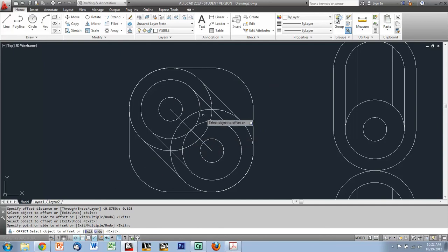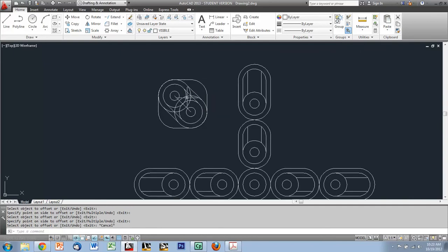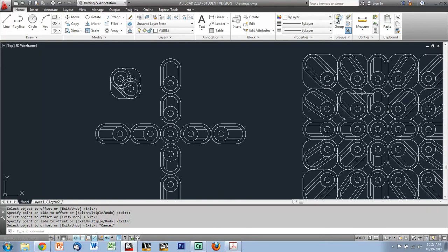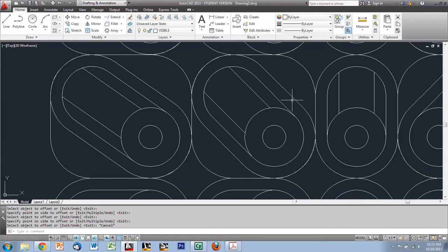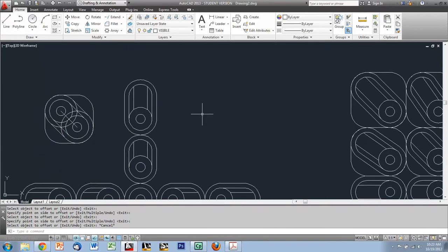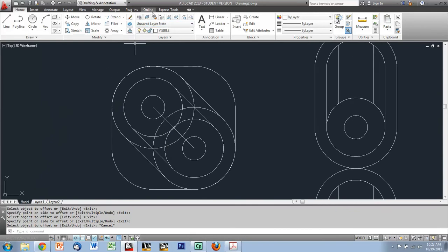And now we've got everything in there, but the trick is knowing what to trim out so that you end up with something that looks like this. So my method when I do this drawing is that I like to start at the outside and I go all the way around this, almost like a racetrack, and trim out anything that I come across. This whole outside ring should be blank. So to start with, I'm going to do that. So I'm going to use my trim tool.